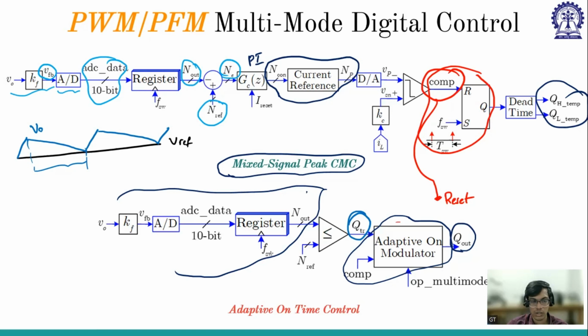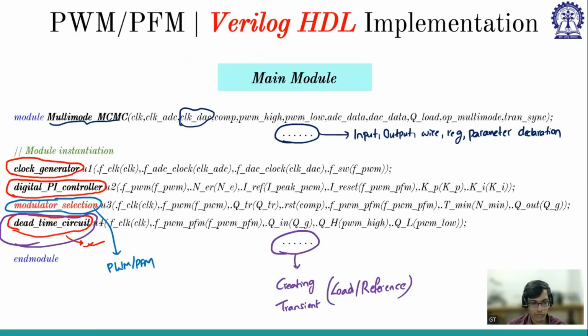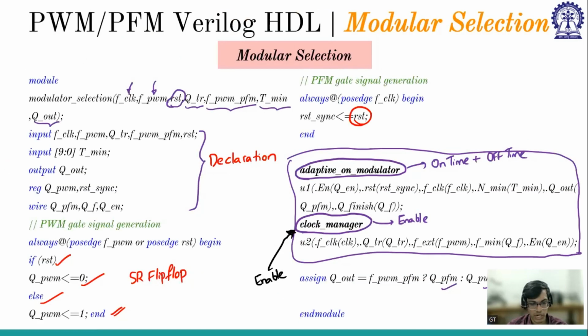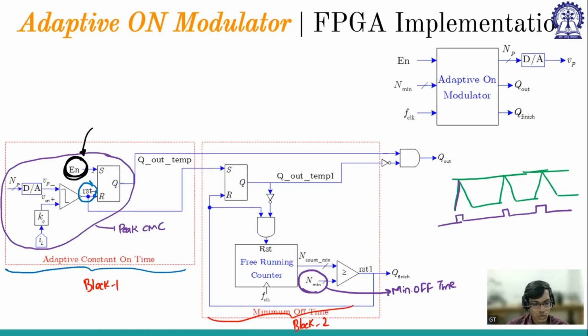The minimum value for which it has to be off is decided by someone, right? Like we are deciding it. Again, it could be a fraction of the off time. Say the off time is 1 microsecond. I can choose the minimum off time to be 1/10 of the off time, say 100 nanoseconds. Is it the user's choice? Yes, it is completely the user's choice.